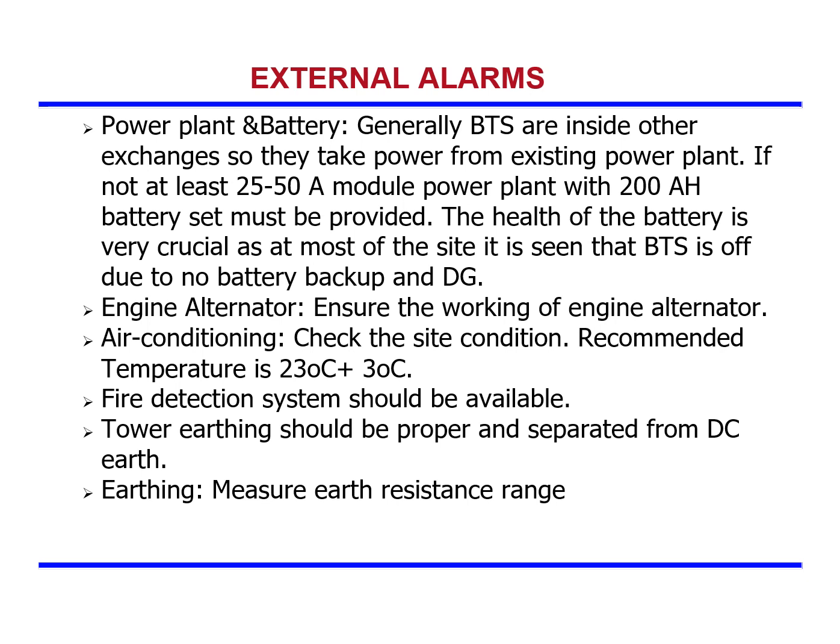Air conditioning condition should be checked. The recommended temperature is 23 degrees Celsius plus or minus 3 degrees Celsius. Fire detection system should be available. Tower earthing should be proper and separated from DC earth. Measure the earth resistance range and ensure it is within limits.